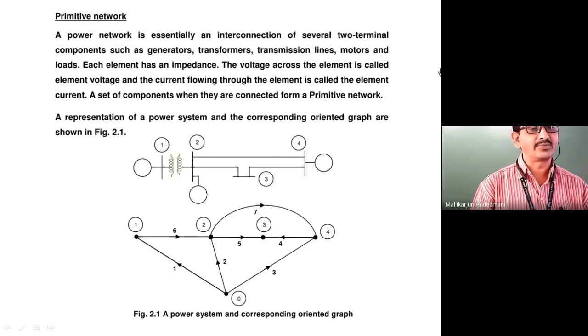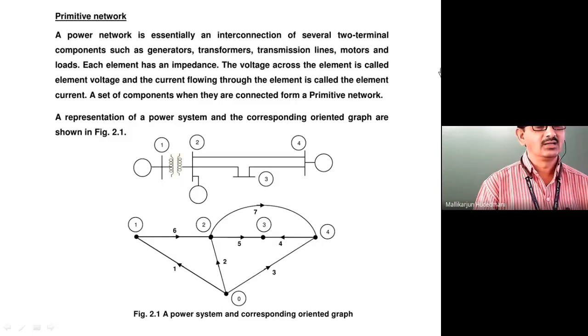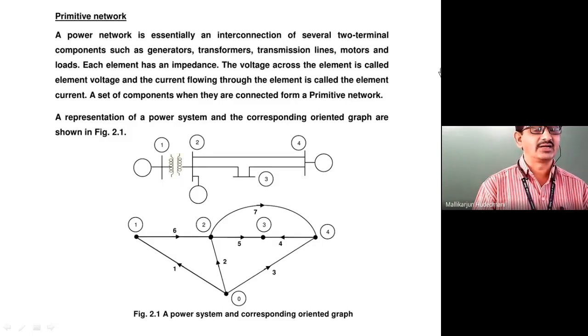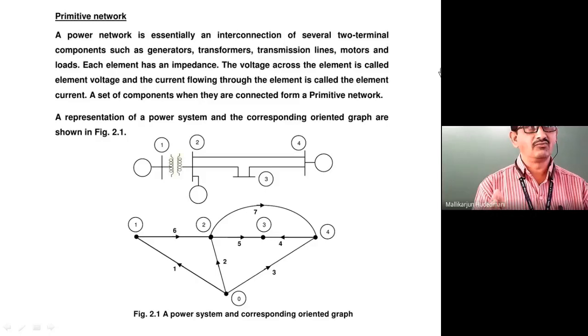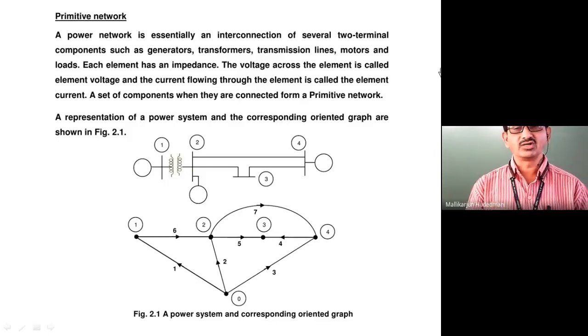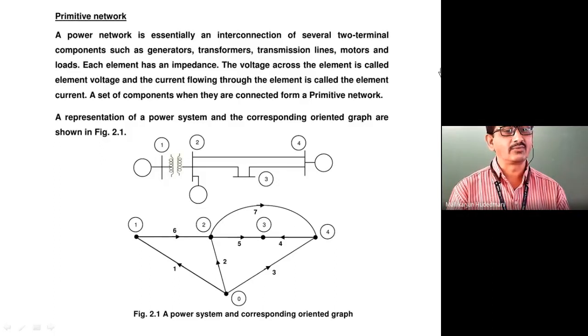Then the matrix A cap shall be 7 cross 4: 7 elements and 4 buses. Then I can definitely frame matrix A for that. If I account for 0 also, it becomes A cap, and at that time it becomes 7 cross 5. That is the complete, or full, matrix A cap or A bar. If it is reduced by one column, the representation pertaining to the reference bus, that will automatically be termed the reduced impedance matrix, wherein information related to the reference bus is eliminated from the representation.